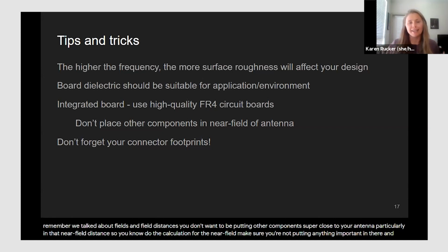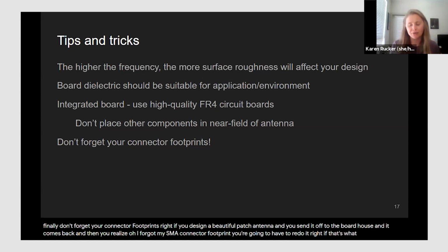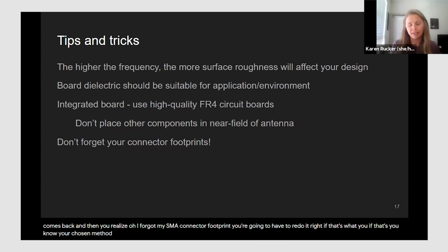And finally, don't forget your connector footprints, right? If you design a beautiful patch antenna and you send it off to the board house and it comes back, and then you realize, oh, I forgot my SMA connector footprint, you're going to have to redo it, right? If that's your chosen method of connector. Obviously, it differs depending on what you choose for your design, but don't forget it. And double check your measurements for your connector footprints on your boards and make sure that they match.